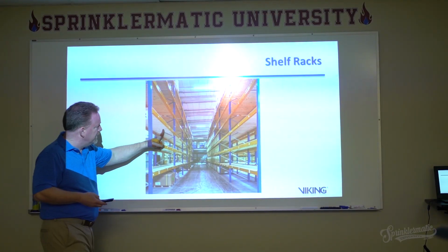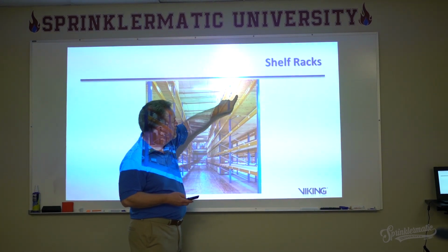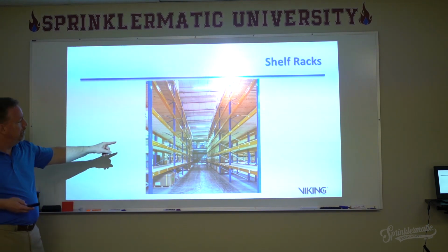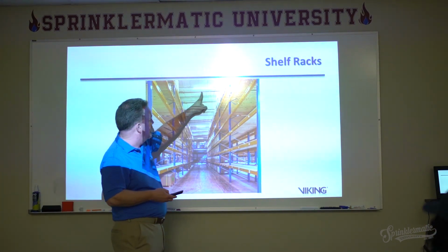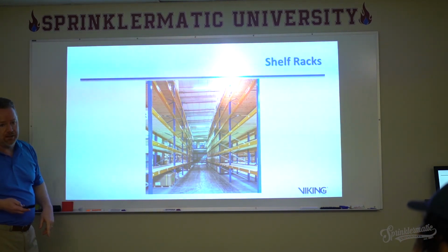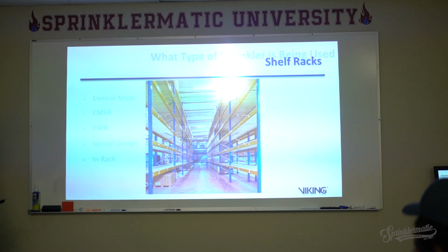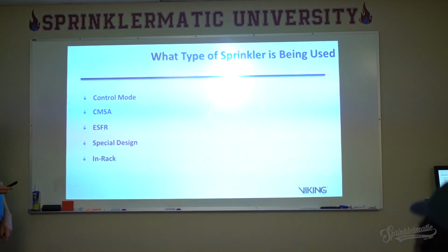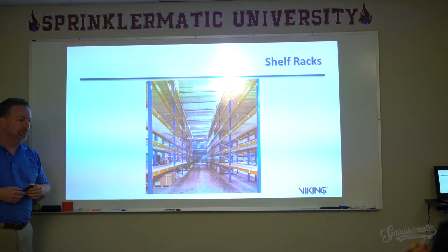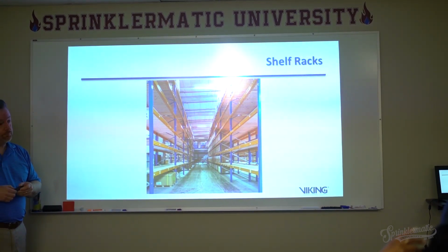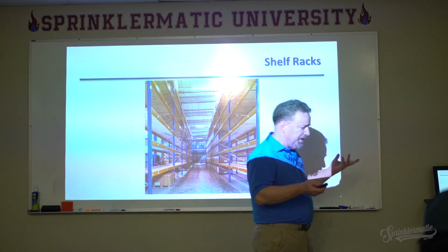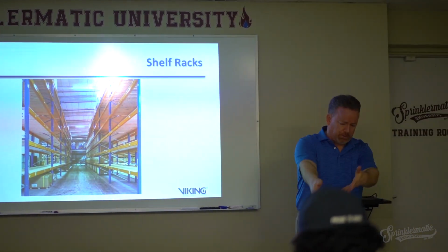So this is permitted. Here's solid shelves in the racks. That is permitted, but you've got sprinklers up in the ceiling here. What I'm not seeing right at the moment is anything down below those solid shelves. So on a company inspection, you only have sprinkler heads at the ceiling level, and they're high capacity. Okay, they're ESFR storage level sprinklers, one of those we're going to talk about.